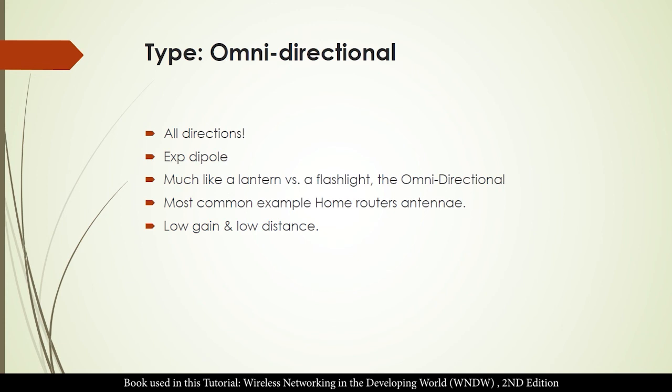In the same manner, the omni antenna works like a candle or a lantern. It will spread the signal in every direction except for the upper part and the lower part. As compared to that, the directional antenna or the super directional antenna will work like a flashlight, or like a spotlight.